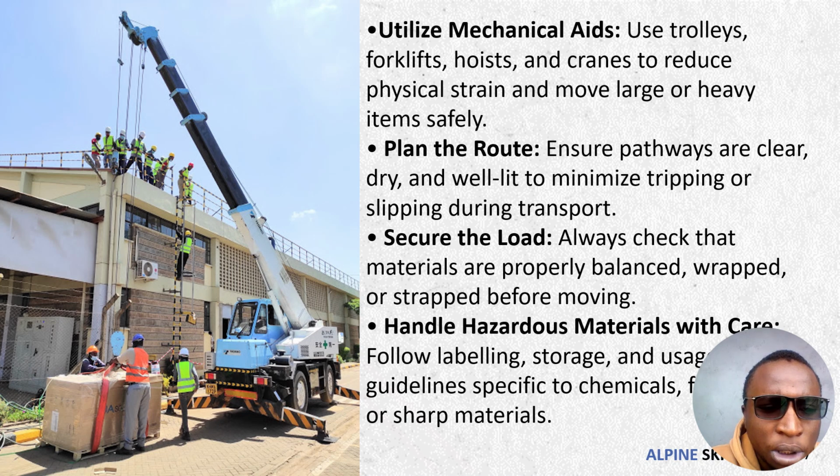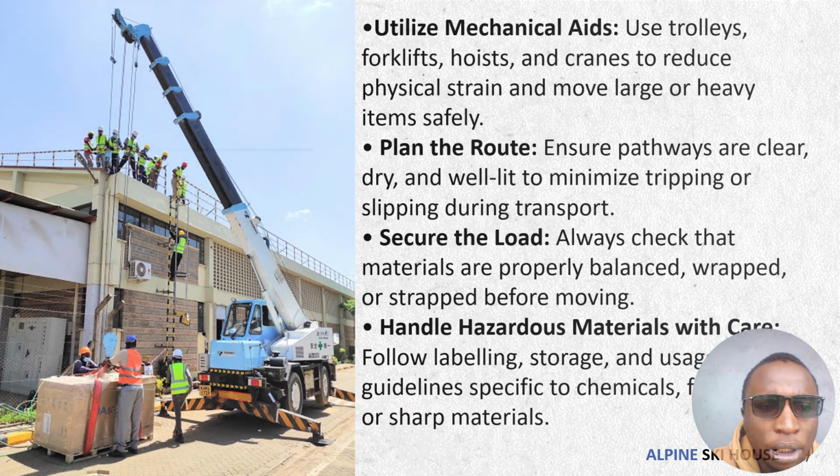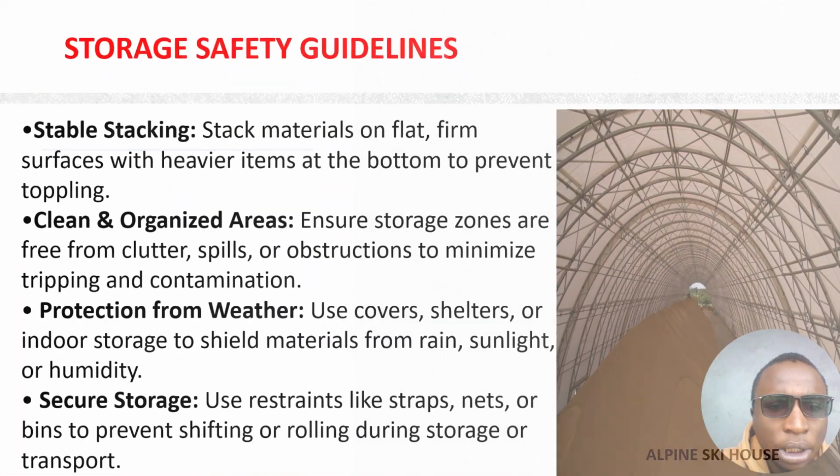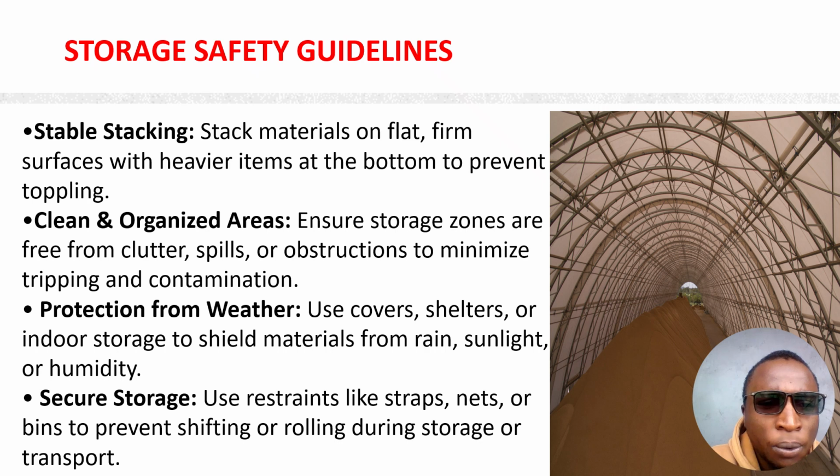The other one we are going to talk about is the storage safety guidelines, starting with stable stacking. When you say stable stacking, you mean you are supposed to stack materials on flat, firm surfaces with heavy items at the bottom to prevent toppling. What I mean by toppling is that if you place heavy materials on top of light materials, or the base is not flat and strong, the heavy materials will fall to the ground.